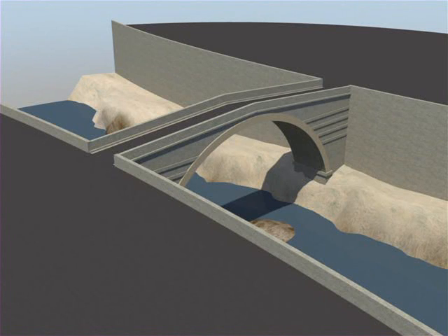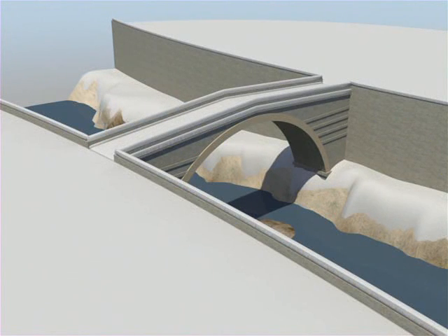By following the load path, starting at the point of application of the loads and following it all the way down to the structural foundations. The principal live loads acting on the structure are pedestrians, vehicles, and snow accumulation in the winter. Let's start with a snow load, which would typically be uniformly distributed along the full length of the bridge.